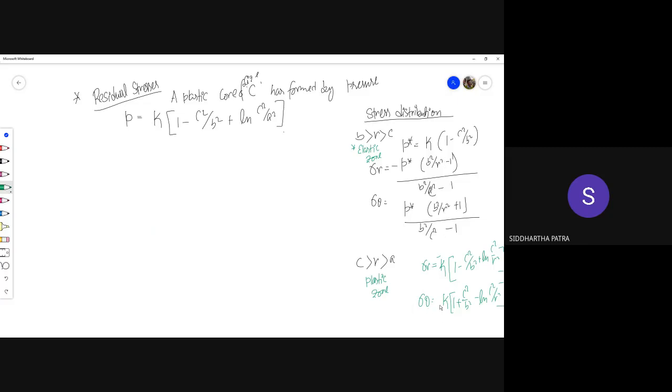Okay. So we need to have the stress state before unloading. So we are somewhere over here. Okay. So in the elastic zone, we are somewhere over here, and we'll simply be doing elastic unloading. Okay. And that is to say, we'll not be reducing the stresses in the elastic domain by the same amount as these two. Okay, that would be some other stress, which could make us land up in the compressive side. Okay.